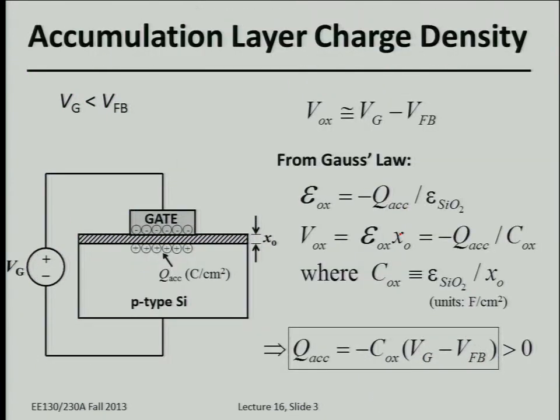As a capacitor, we're interested in the basic equation that describes how a capacitor works. Q equals CV, that's right. So let's derive this equation for Q equals CV on this slide. From the previous slide, I explained that the voltage drop in the silicon is negligible, at least approximately.